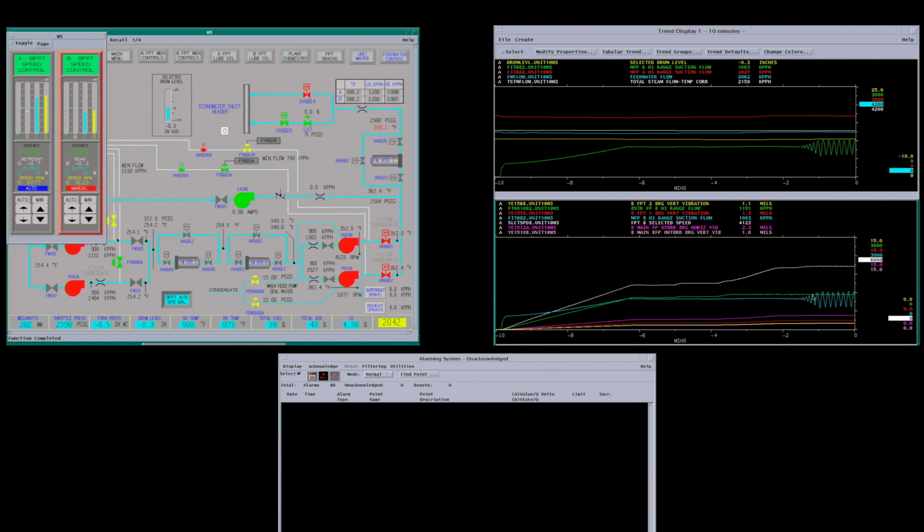You see we're getting the booster pump swinging too now a little bit. So this is something you don't ever really want to see in a power plant with your feed pump. If you get this situation, you got to drive the flow up quick or trip it. But you don't want to hang here. You can tear up thrust bearings and do some other damage to the equipment. Right now I'm just kind of curious how far it's going to go. Seems to be getting worse and worse as it goes.